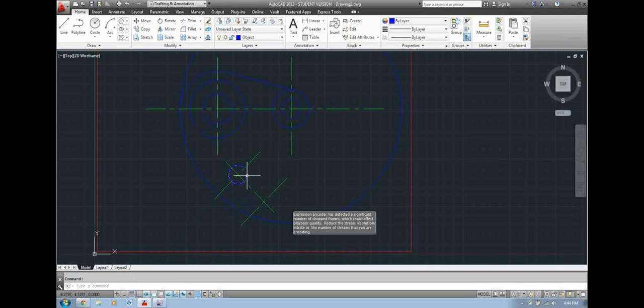Huh, well, that didn't work. So I just hit undo to undo that. I'm going to try and figure out why that messed up. Start point, 0.5 in this direction. Oh, I think I figured it out. It's allowing me to type in degrees. I typed in a length. I said I wanted it to be 5 inches in this direction. So instead of doing that, since I'm on this polar snap, I'm just going to click right there. And now it's got the distance that I wanted. Let's try that again on the other side.